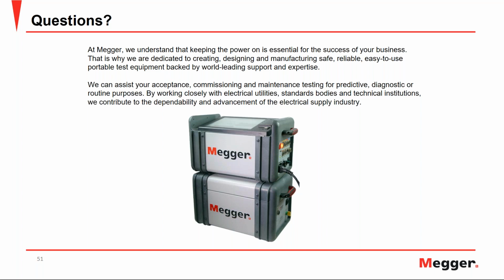Again, these are some very good questions. So the dissipation factor or power factor test is not a destructive test. And the reason being is that you do not exceed the rated voltage of the winding, as Charles mentioned in the presentation. And not only that, you're only applying that voltage for a very small amount of time.